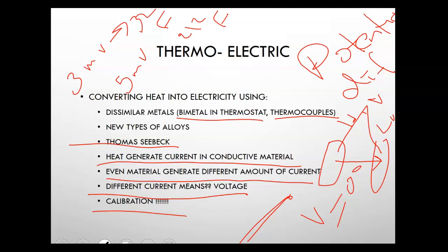We keep taking. Why did we use 32 and 212? Because we know these are the temperatures for freezing water and boiling water. So these are constant at atmospheric pressure, so we can use that to calibrate. There are more sophisticated ways to calibrate thermocouples, and usually they do not go out of calibration very quickly, and they have improved a lot. So the calibration can tell you what voltage in between will correspond to what temperature. Just some information about that.